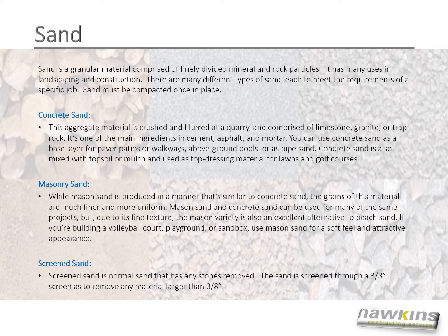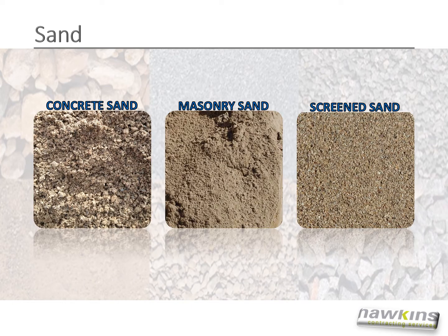Screen sand. Screen sand is normal sand that has any stones removed. The sand is screened through a 3/8 of an inch screen so as to remove any materials larger than 3/8. Pictured here are the three sands: concrete sand, masonry sand, and screen sand.